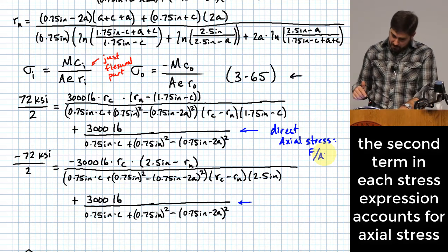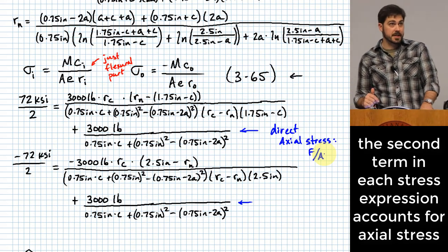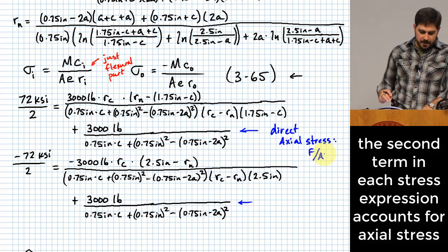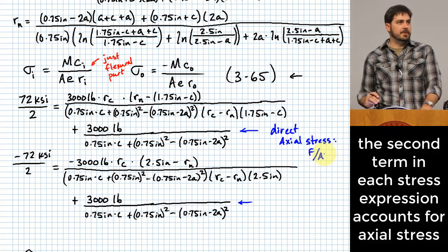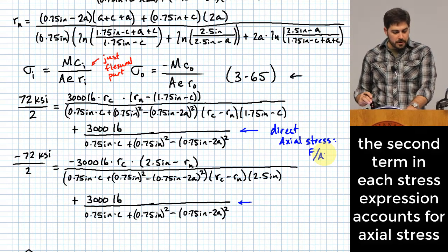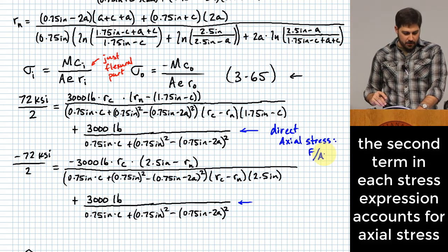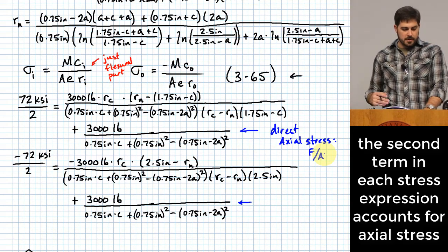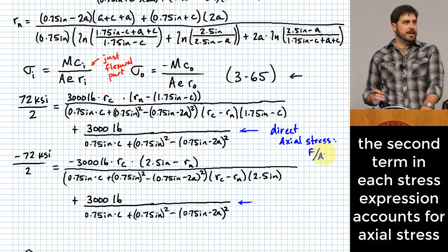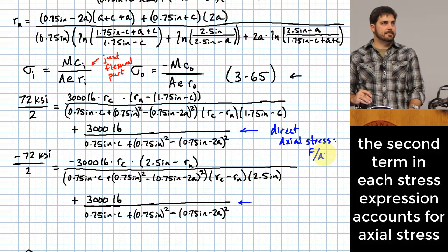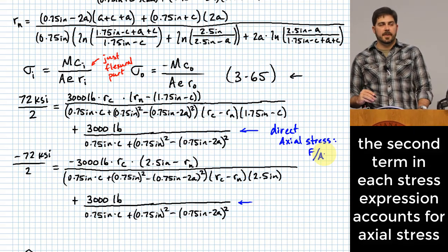Yeah, actually at the bottom of page 133, it's in an example problem that they have in the textbook. And they're doing a very similar type of thing where they're adding force onto a hook. And you'll see there it's an equation labeled 2. What they're doing is adding just a direct F over A amount of stress, which is a direct axial stress, to an amount of flexural stress, which is what you find using equations like 364 or 365. Good question.